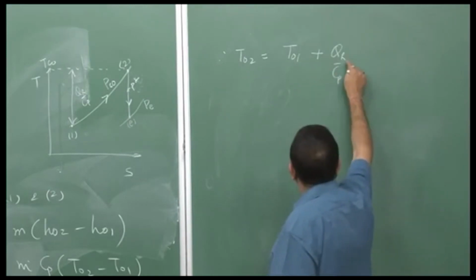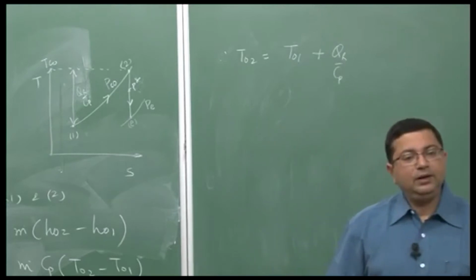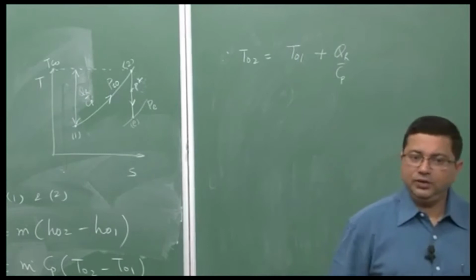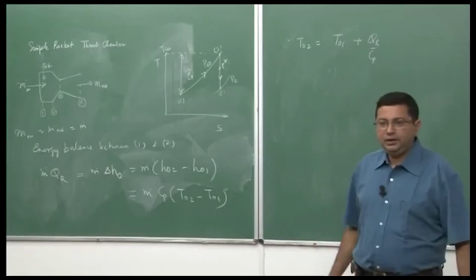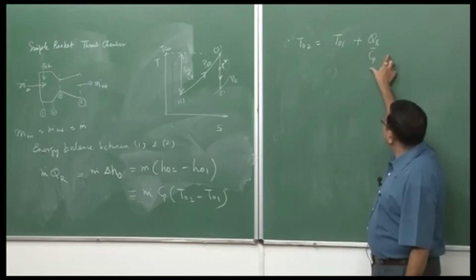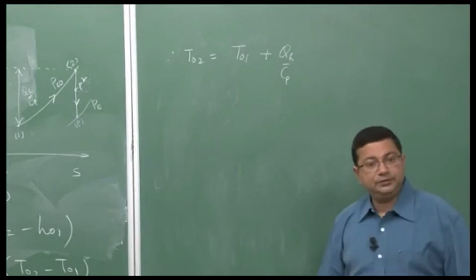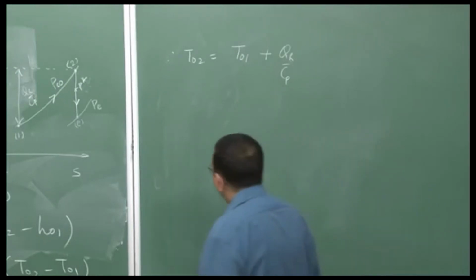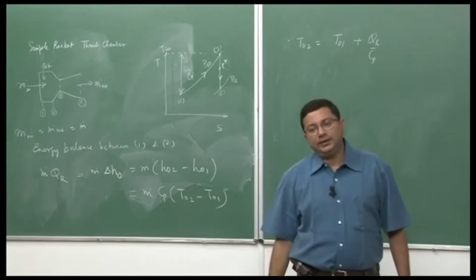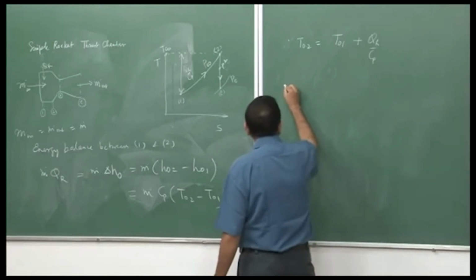So, if the fuel and oxidizers are given, the propellants are specified, then for a particular propellant combination there is a particular heating value Qr. So, that is a known quantity. Then from the product Cp is also a known quantity. So, if these two are given, initial temperature is given, then we can estimate the final temperature. Now, in the nozzle the flow is isentropic, and we have proved that for an isentropic flow,